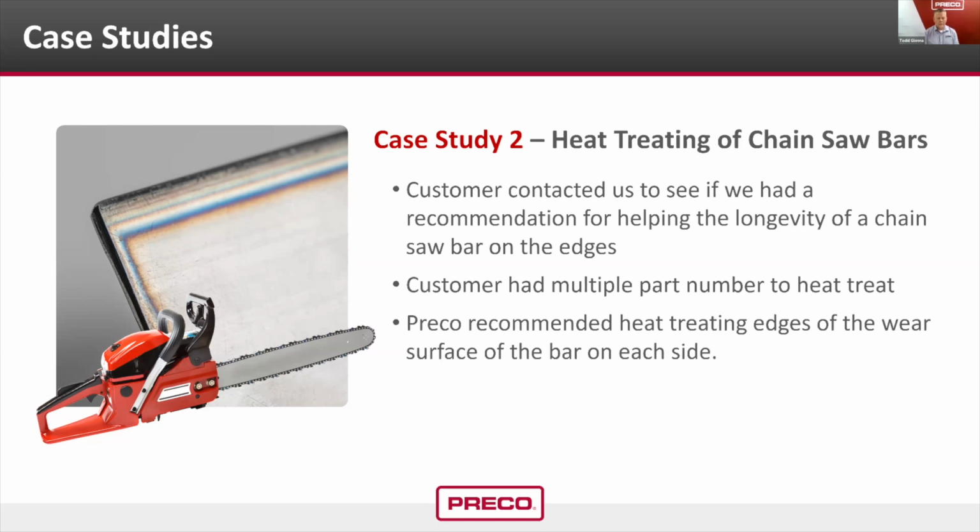And again, this program, I would say, has 30 part numbers, and we are able to use universal tooling. With programming changes on the CNC laser system, we are able to go from part to part without tearing down tooling and setting back up and requalifying. We're able to make computer program changes to go from part to part, which again is a good indicator of how flexible using the laser is for heat treating various parts.